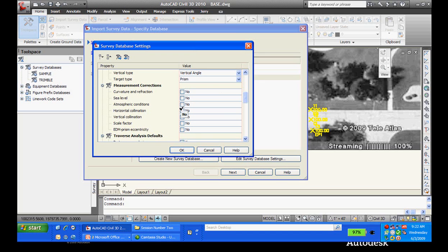All right, there's one other thing, and that was what the individual mentioned here before we started this morning. Generally, it is the sea level correction that we'll want to make sure is checked on. The way that we were applying the correction was a slightly different calculation than what Trimble did. Ours was based solely off the instrument height. Theirs was based off the average elevation between the instrument height and the elevation of what was being shot.